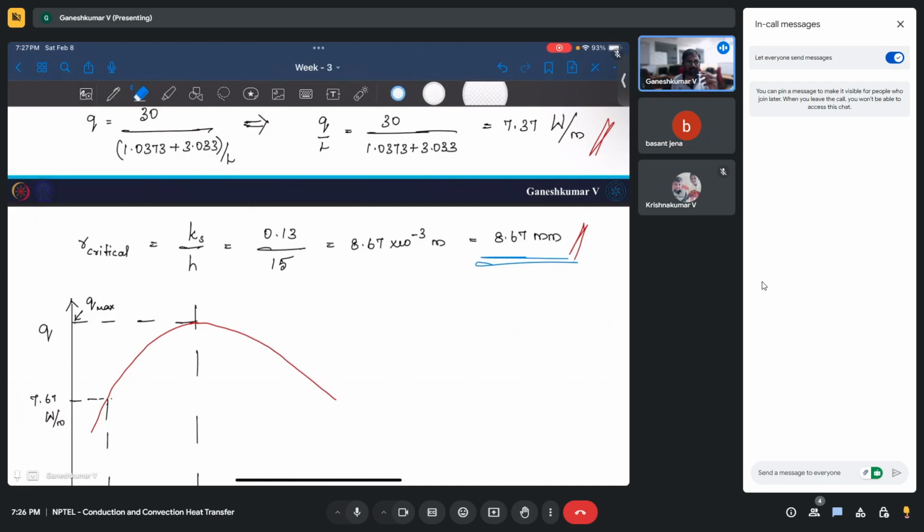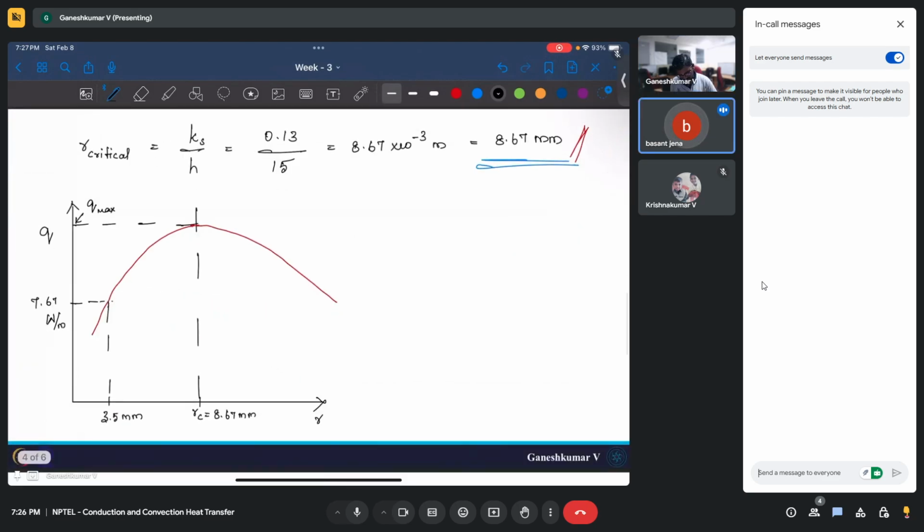So currently the thickness is 2 mm, so I can increase the thickness to 7.1 mm, and at that point I still will have 50 degrees maximum temperature, it will still be 50 degrees Celsius. However, the Q, the current which I'm passing through the wire, can be higher. Is that clear what I'm trying to say? Could you please repeat it, sir?